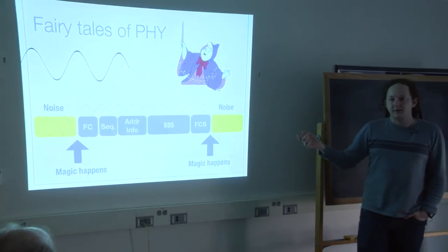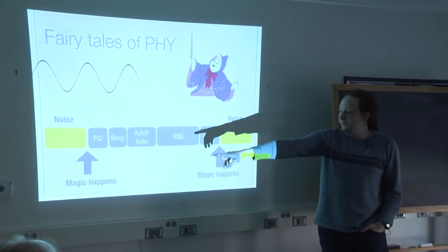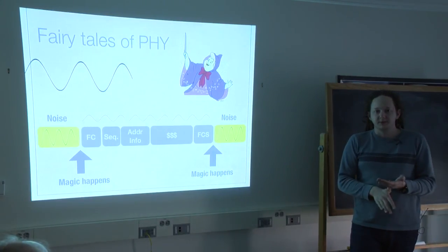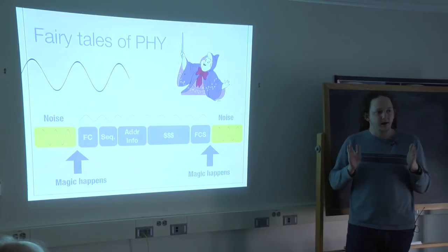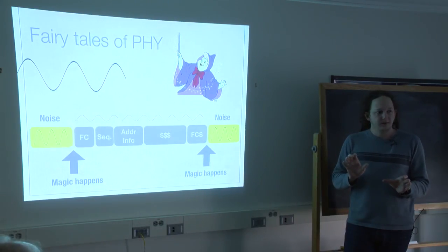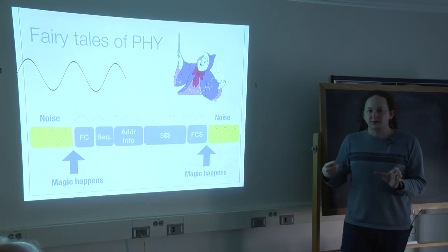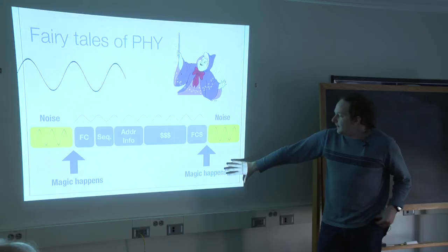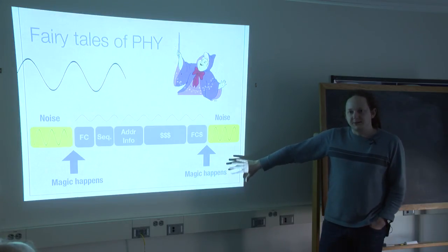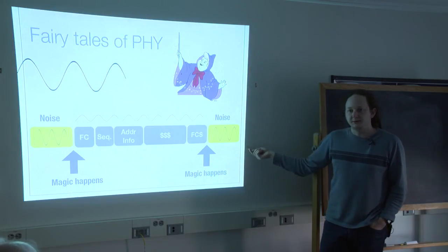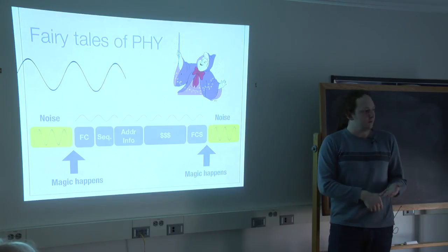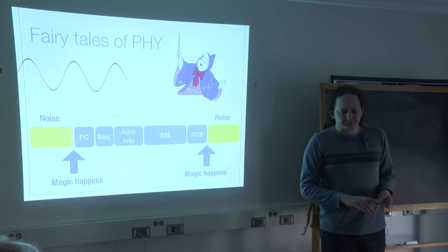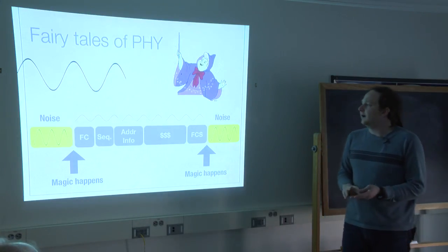The easiest way to implement the magic is that at the very beginning of the packet, on the left, you have a start of frame marker. This is a symbol that tells the receiver where the packet begins. And then you have a length. And then you just tick off the length number of bytes by having a counter that counts downward to 0, running until the end of the packet. And then you don't actually mark the end of the packet physically. It's just that the counter expires. And this is how 802.15.4 does it. This is how, in one way of thinking, Wi-Fi does it. Although Wi-Fi has a bit of a complication on top.